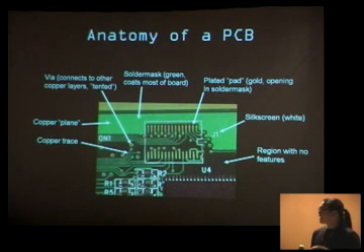Now I'm going to get into actually reading the PCB itself. If you take a circuit board and look at it, it oftentimes looks something like this. You have bright green areas and dark green areas, some areas that look gold, and so forth. The bright green areas are where there's copper underneath, where there's conductor underneath. Dark green areas have no feature. The areas that look bright and shiny are where the solder mask has been peeled back so you can solder to it. Copper normally looks copper colored. The reason it looks green is you put this coating over it so you don't accidentally short things together as you put the board together.